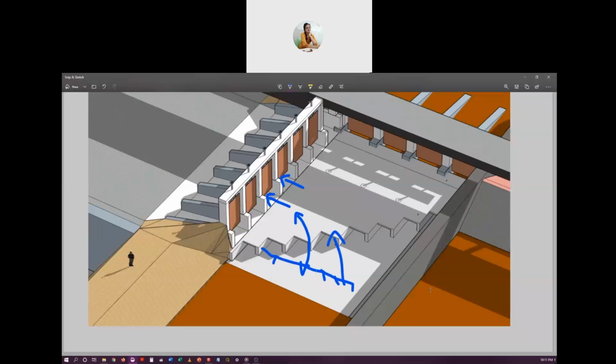Once we adjust the tunnel lengths so that this tunnel is the longest and this tunnel is the shortest and so on, then because the water velocity is in this direction, a major part of the lower portion of the flow will enter these tunnels, and along with that, sediments or silt will be trapped inside these tunnels.